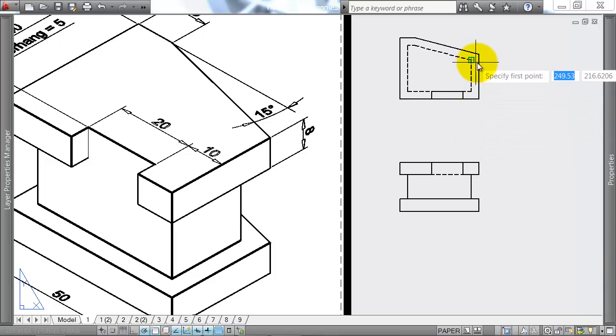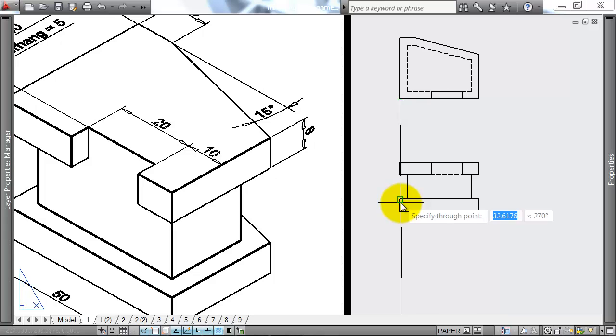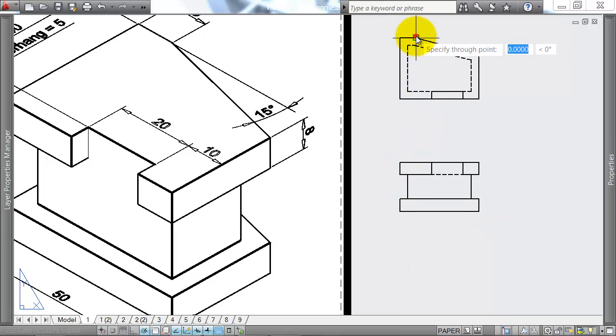We've got a feature in line with every one of these edges. So in line with this edge, I've got that. In line with this edge, I've got this feature in here. In line with this edge, I've got these features. In line with this edge, these ones. So I can go around the whole way through and check that for every corner I've got on this view, I've got at least one line on my front view. But these back corners I haven't located yet.